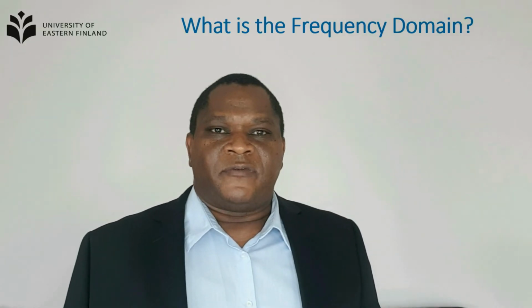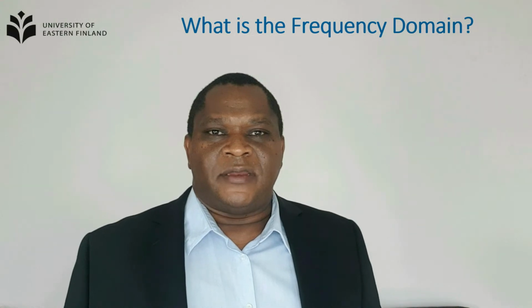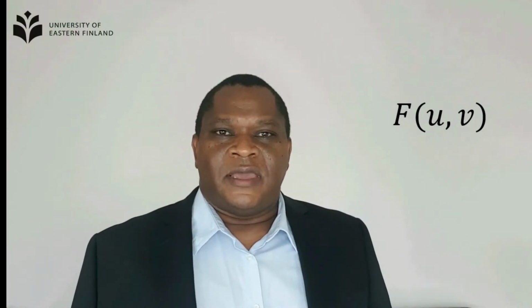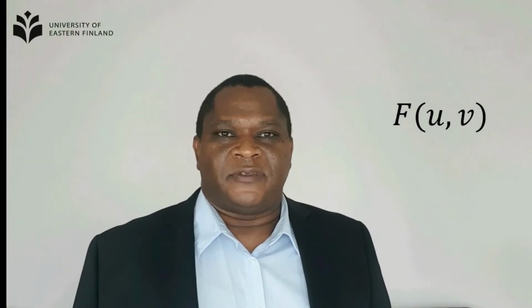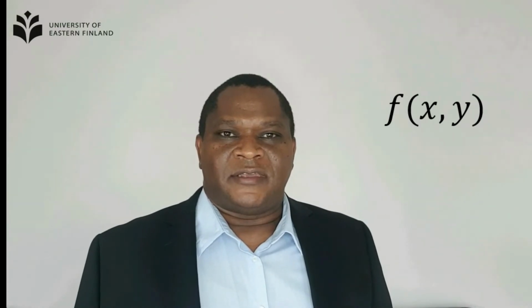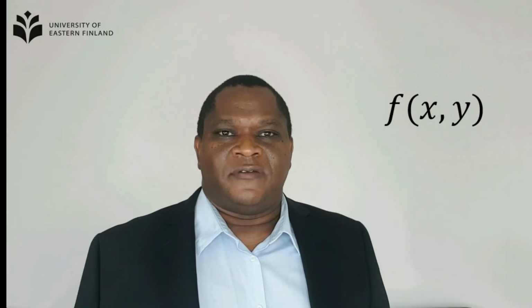Now, answering the above question, the frequency domain is simply the coordinate system spanned by the discrete Fourier transform of the input image, F of u, v, with u and v as frequency variables. This is analogous to the spatial domain, which is the coordinate system spanned by the input image function f of x, y, with x and y as spatial variables.